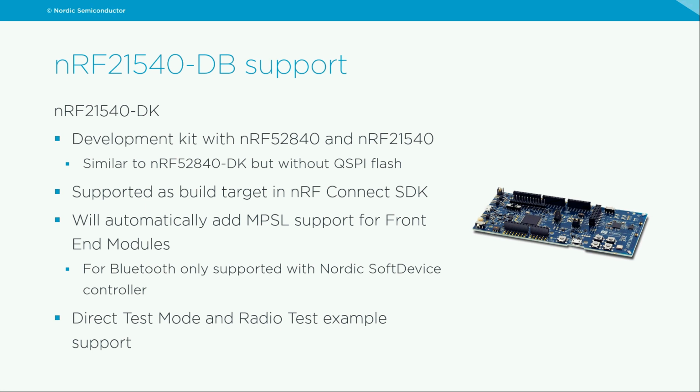Have in mind that for Bluetooth, we only support this with the Nordic soft device controller. So there's no support for the front-end module together with the Zephyr controller. So if you want to use the front-end module and if you want to use MPSL, you have to use the Nordic soft device controller. One of the additional feature updates we have done to the nRF Connect SDK version 1.7.0 is that the default controller for Bluetooth Mesh is now also the Nordic soft device controller. So this is why we can be able to support also Bluetooth Mesh with the